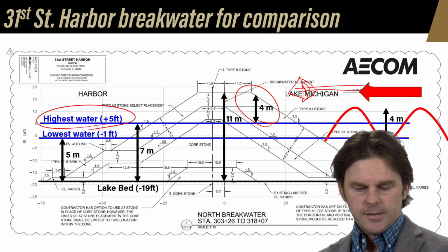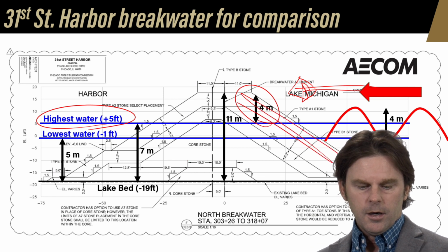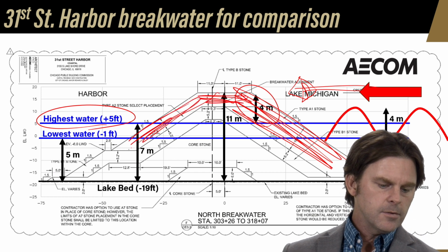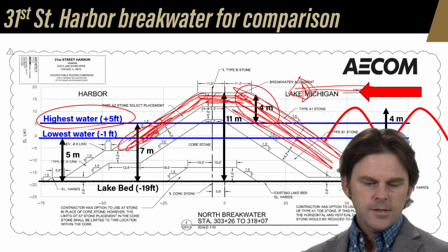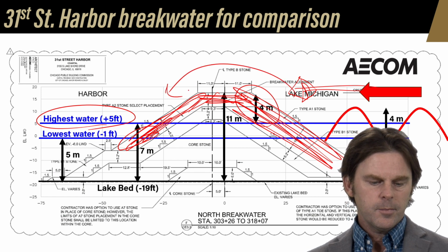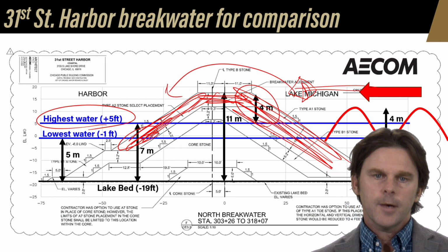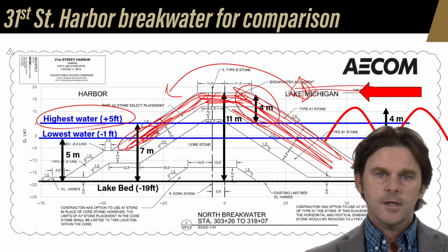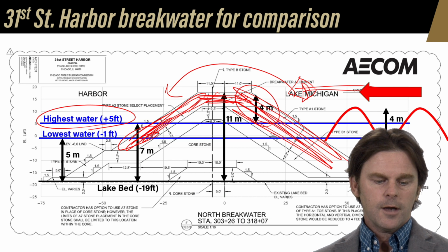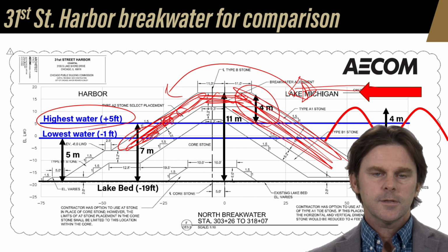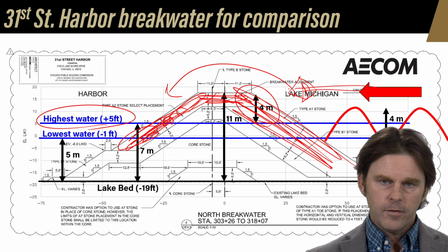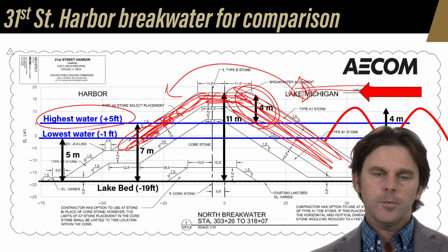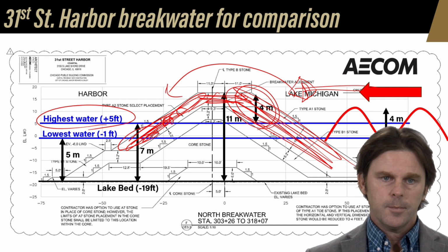But I digress. Notice that there is armor all on the wave side, all on the crest, but actually all the way down 2/3 of the backside. So this structure, because it's armored on the backside pretty heavily, can withstand a significant amount of overtopping, and undoubtedly that was factored into the design that you see here, making sure that the armor and the placement was okay for the design wave and the amount of overtopping that wave would cause, okay? So that's how you're able to do much less freeboard than what you would calculate for no overtopping.